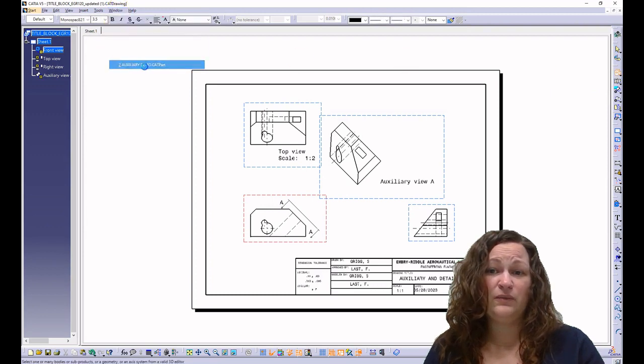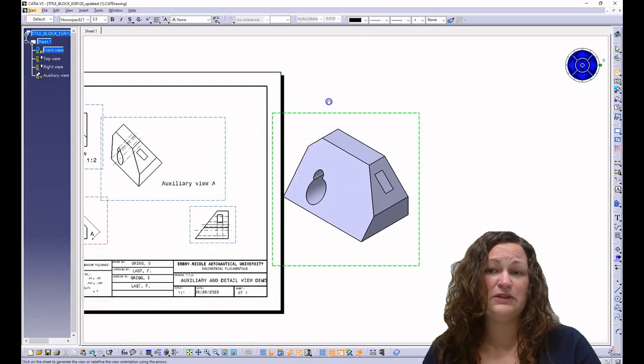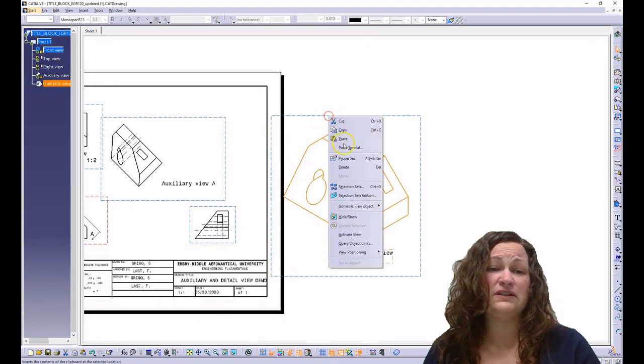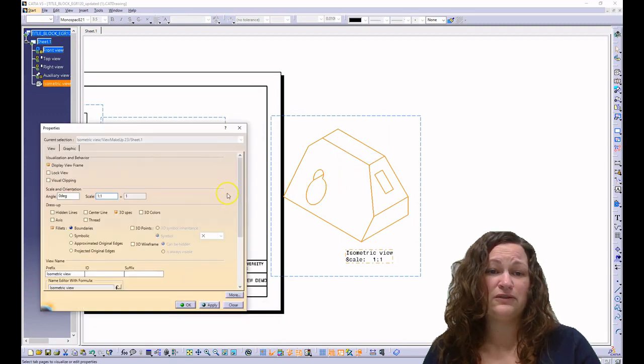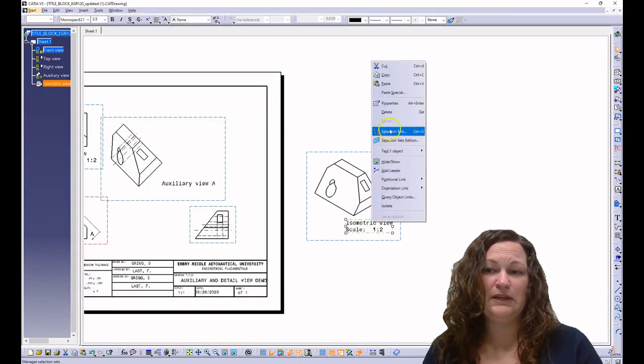Now here, when we click on the inclined surface, it's fine because it's going to bring over my isometric view in the orientation in which it is shown. So you got to make sure that you update that into isometric view before you click on it to bring it over. It will not update it or rotate it. You have to do that manually.